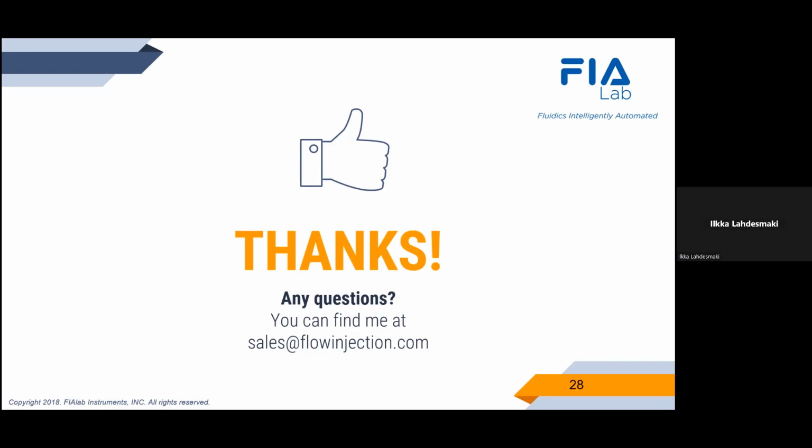And that configuration was actually not at all tailored to low-end analysis, but more tailored to high-end analysis, because that seemed to be where a lot of the lab's needs were. They wanted to extend the calibration range as high as possible on the high end and did not care so much about the low end. If need be, that method can easily be reconfigured with a longer sample loop so that you can reach a quantitation limit of, let's say, 10 ppb and a detection limit of single ppbs.